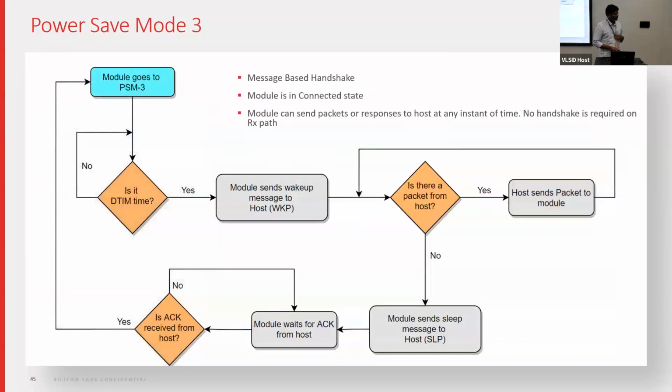From the device side, is there any recovery mechanism? I think your question is whether, when the wireless device wakes up and finds that the bus has gone, the train has gone, and now it cannot catch the train, is there a way for it to correct itself? Yes. It will see that it has missed. It will stay awake until the next beacon. It will receive that traffic, the time sync signal, and then it will reset its timer and, if necessary, recalibrate.